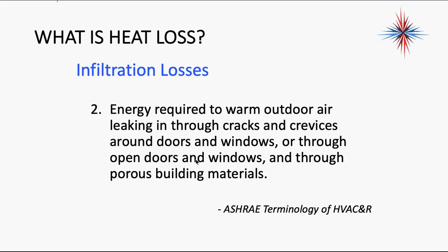Infiltration loss is the energy required to warm outdoor air leaking through cracks and crevices around the doors or windows, or through open doors and windows, and through what we call porous building materials. We don't have many of those. But if you feel a breeze that's cold, that's infiltration. Now, some infiltration is good infiltration. Some infiltration is not good infiltration.